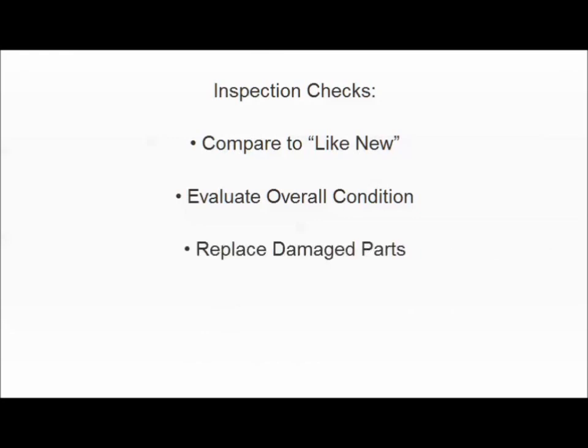Only replace damaged parts. Galling, scoring, and cracks indicate immediate replacement. Parts with even wear or minor chipping should be ready for continued service. Once you evaluate the engine using these overall checks, you can be confident you've performed a quality visual inspection.